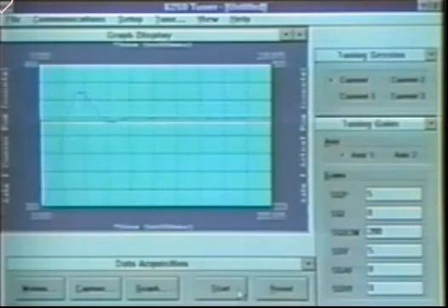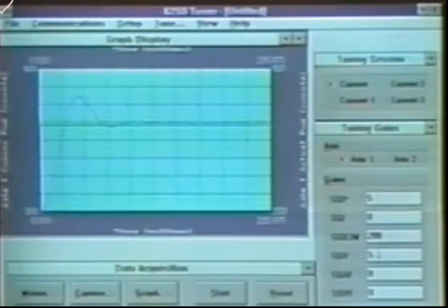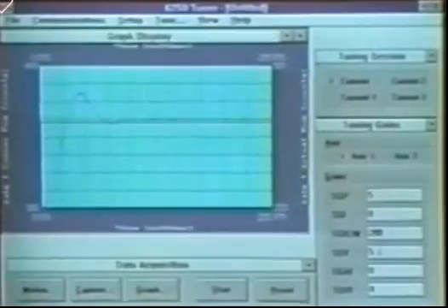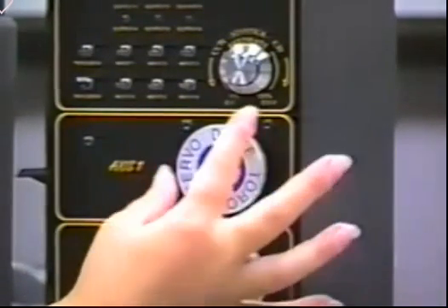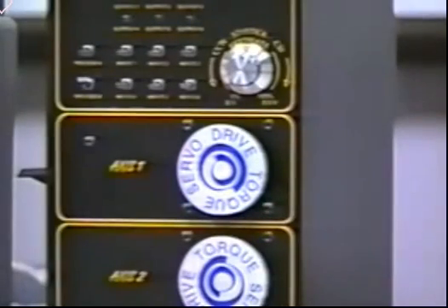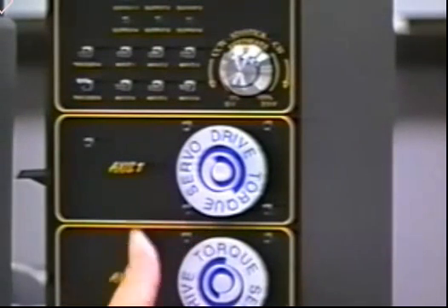This seemed to have decreased our oscillation, and we have a critically damped case, which is what we want for optimal servo tuning. This is the parameter response achieved through ServoTuner. We will contrast a tuned axis with an untuned axis. What affects our tuning had on axis 1? Notice the stiffer response of the system. Compare that to the behavior of the untuned axis.